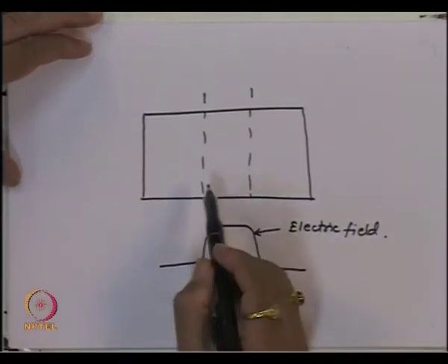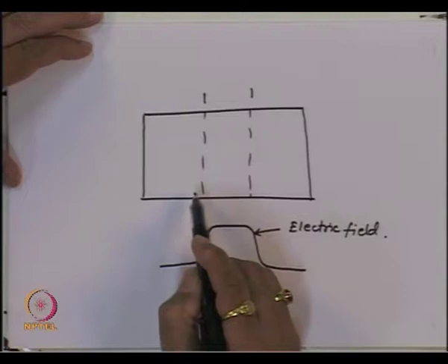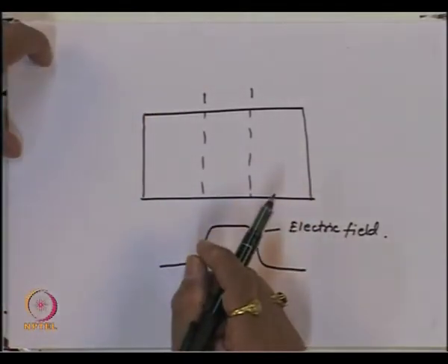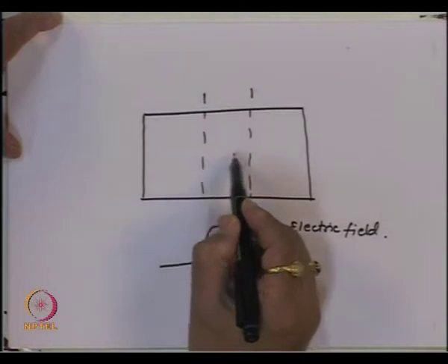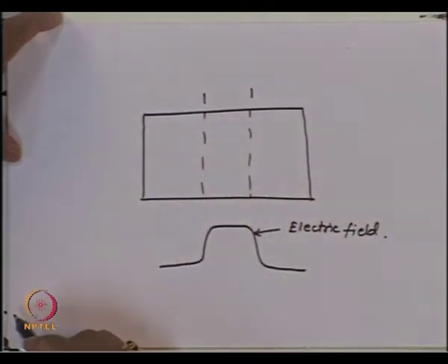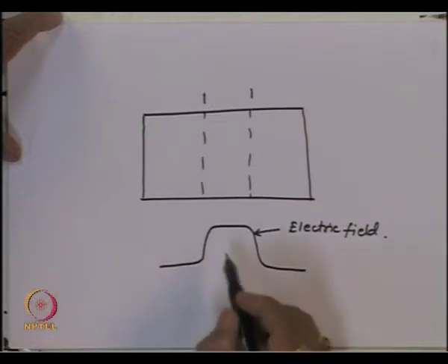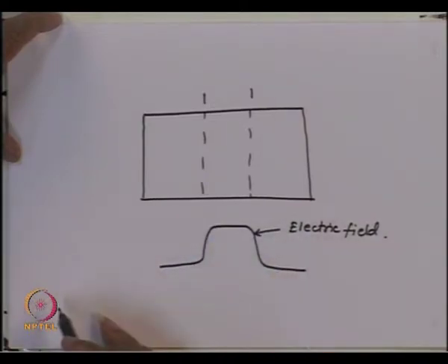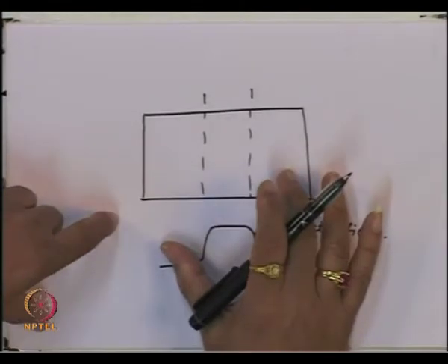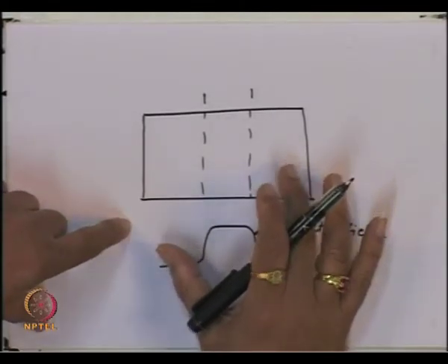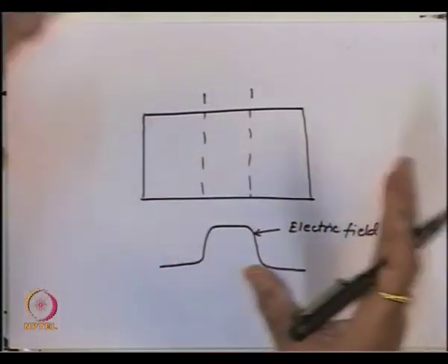So, now to make the absorption of the photon more efficient, first thing we have to do is we have to increase the length of this region, the depletion region, over which the electric field is practically constant. Also, since this device is a reverse bias device, we know that the depletion width varies as a function of bias voltage. So, we want that the region over which the absorption of the photon takes place, that should be practically independent of the bias voltage.